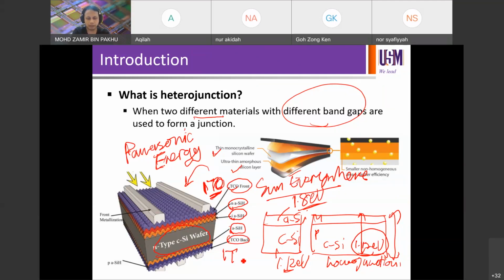Remember, in the last lecture, we discussed non-metal contacts, right? You mentioned semi-metals and degenerate semiconductors. So this is the real device that we are looking at now, with ITO contacts. Even though you can argue that they also have metal contacts on top, some of the conduction process, the extraction of the carriers, is done in the ITO layer, the purple one.